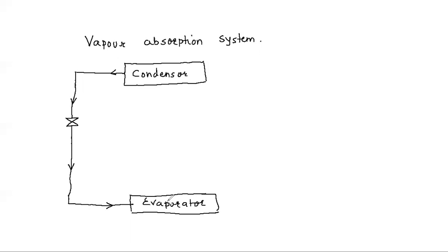you will have three components. So let me list down these three components. So before that, let me talk about the pressures and the phases. So the condenser obviously is at high pressure and the refrigerant is liquid, right? Condenser means it is a high pressure liquid refrigerant because it is already condensed, okay? And it is condensed because of heat rejected by the condenser. Heat is rejected by the condenser, okay?